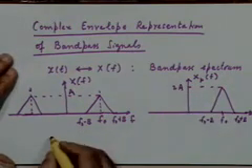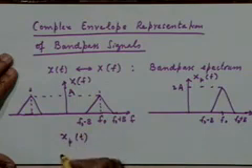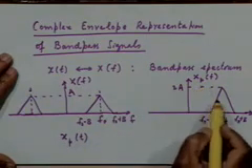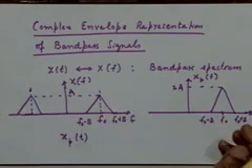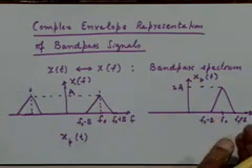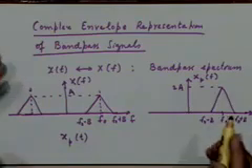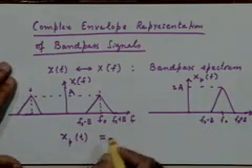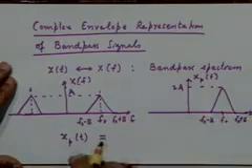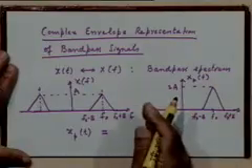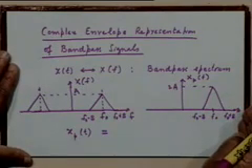And I know that this xpt corresponding to this spectrum would be a complex valued signal whose real part is xt and whose imaginary part is x hat, the Hilbert transform of xt. Can I see this spectrum in a different way? Can I see this spectrum as a translated version of some spectrum around 0? I can see that. Imagine a spectrum of this shape here, and you frequency translated it to f0.